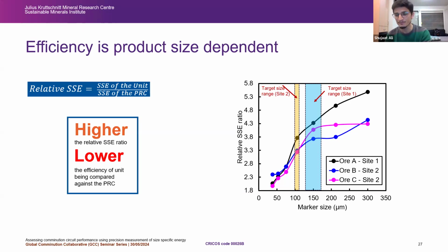But what I want to tell you here is that in the background we have these three different curves showing the grinding data. Look where we are sitting up there, right? We were supposed to produce lots of material in this size range, but we ended up producing lots of fines, which is why we are landing somewhere up there.